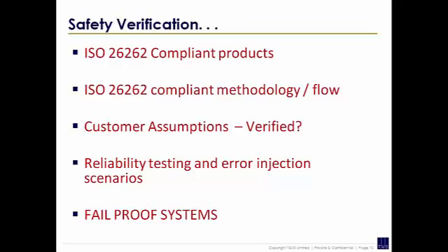But if something goes wrong in the fab, something got stuck, anyway we are doing it in the tester on socket version parts. So within the chip, they may not be required. No, actually it is not just about socket faults. Let's say there's an issue with the flash, and some memory is getting corrupted by itself. So we have to have ECC checks on every flash location. We have to have dedicated ECC bits coming out. Only then we can find out.